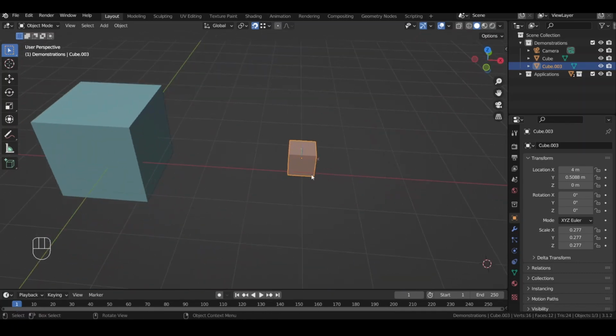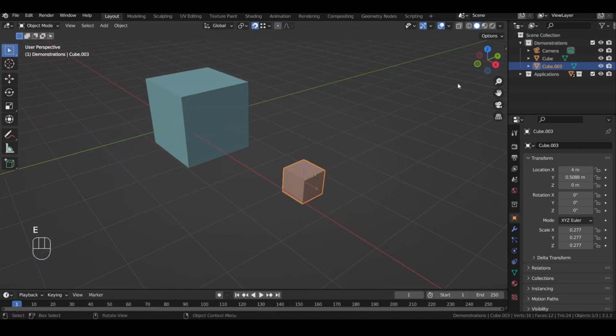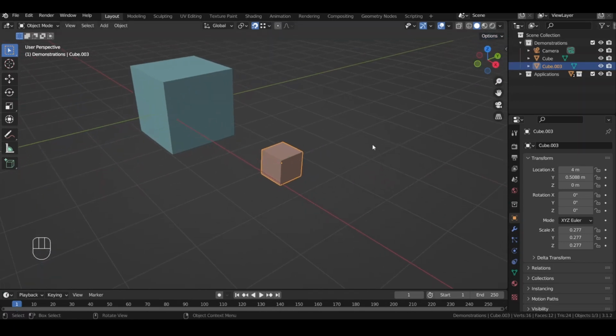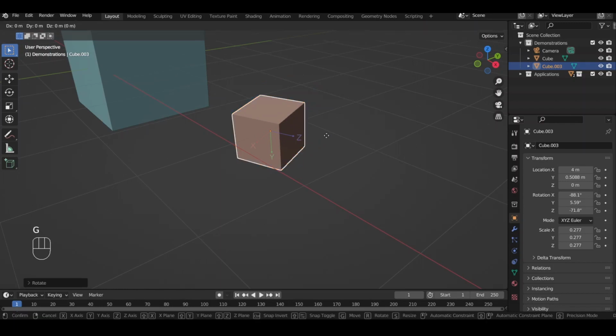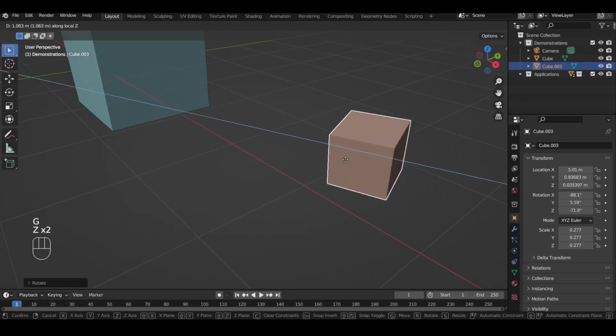affect only origins. You could see that each object has an object local axis, right? And so, as you can imagine, when we rotate a cube, actually, let me turn that back off. When we rotate a cube, the object's local axis rotates along with it. And you could probably guess, this is what helps determine how our local axis looks. So as you can see, the z local axis is pointing that way. And when you try to move it along the local z, as you can see in the top left corner, let me turn that off. You could see that it moves in the same axis.